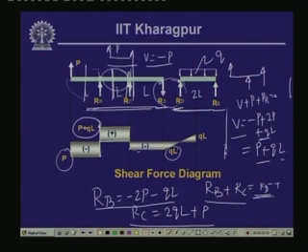So, up to this again it is uniform, since we do not have any load in between, and from Q L here it varies at Q per unit length over a length of twice L, and so minus Q L goes to plus Q L, and here it comes back over here. So, this is the variation of the shear force over the entire length of the beam.